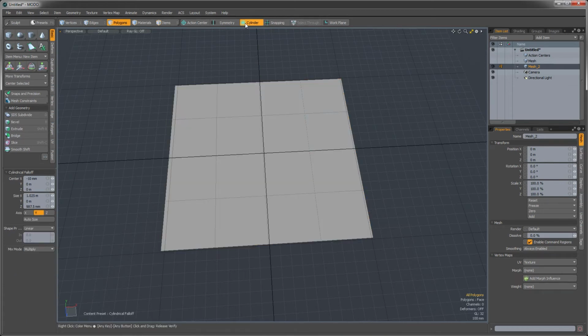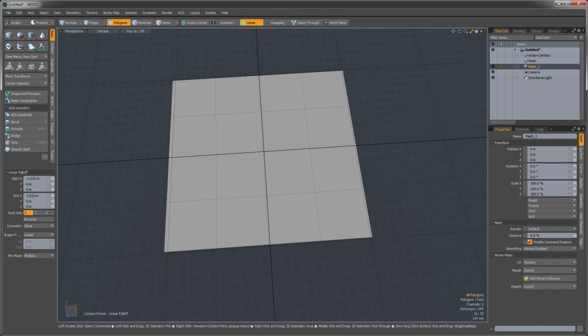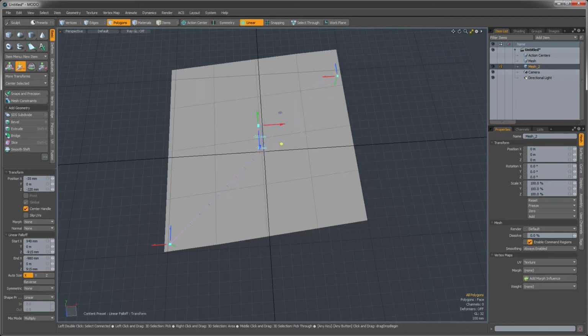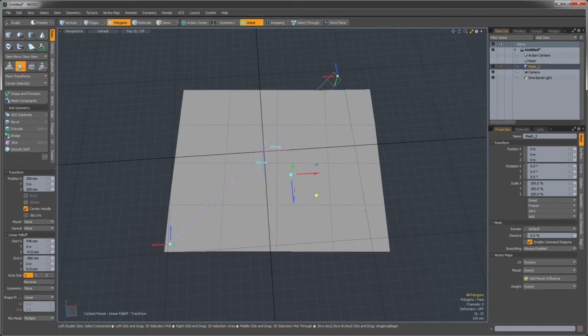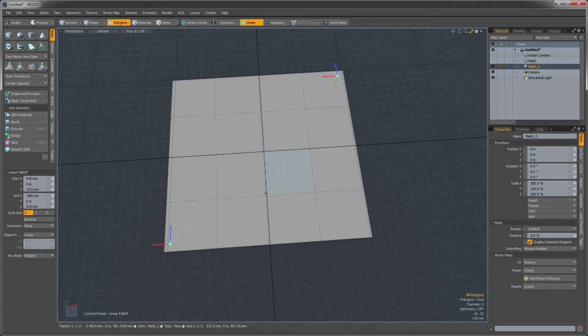So if you want to set up a specific fall off, you can activate the fall off and then use the right mouse button to click and drag and position it out. So the wide part of the fall off up here is where it's going to be affecting your model the most, and this skinny part is where it's not going to be affecting it. So now if we invoked, say, the move tool, it's going to be working in that corner up there more than the lower left hand corner. We can hit escape to drop that selection.